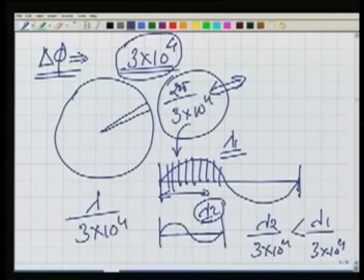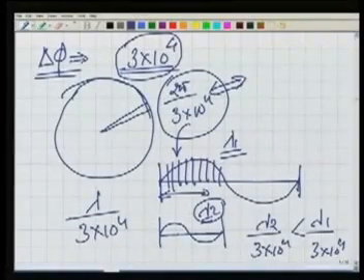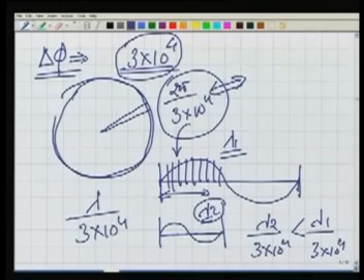So, what we have seen? We can make use of the phase difference measuring instruments. They can measure with certain accuracy. It does not matter what is the value of lambda, because they are measuring the phases. Phase is something like an angle value. Whatever is the value of lambda, small or large, the phase difference can be measured always with the same least count as far as phase is concerned.